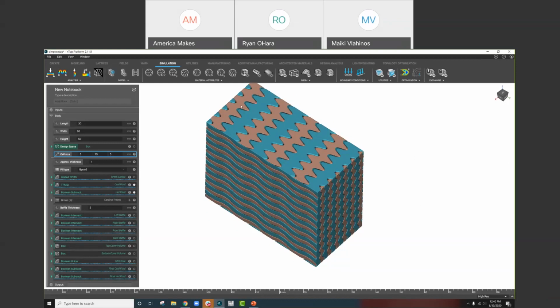We're also going to develop guidelines, as a collective engineering society, that if you get down to a cell size that is too small, it's not worth the effort to try and remove the powder. But you can also argue that at that small cell size, my pressure drop is going to be too high, so there's no reason to go down there anyway.